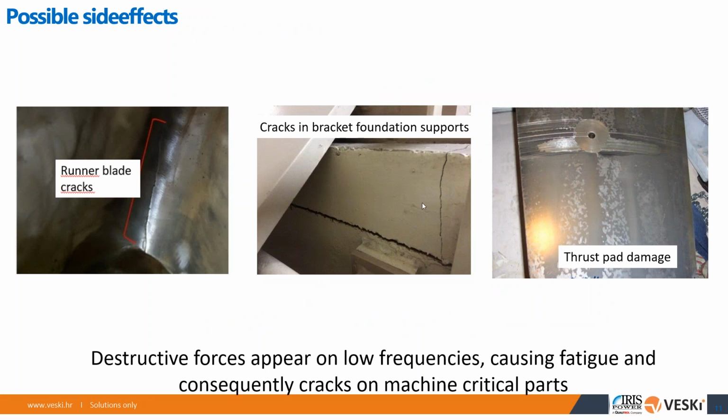Basically, low frequency vibration, when you turn it to displacement, if the vibration is high... let's say you're measuring with an accelerometer, you're measuring the velocity of the vibration on low frequencies, the number doesn't have to be really big, but when you turn it to a displacement, because when you integrate on low frequencies, the number grows.